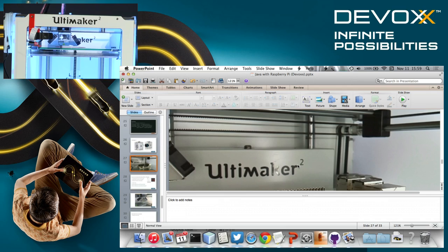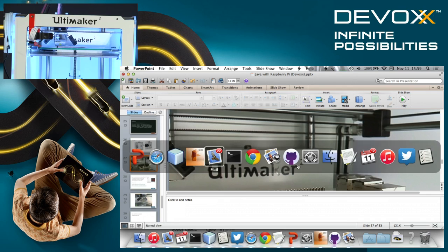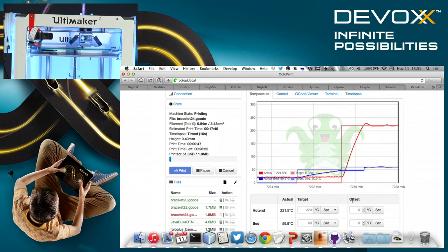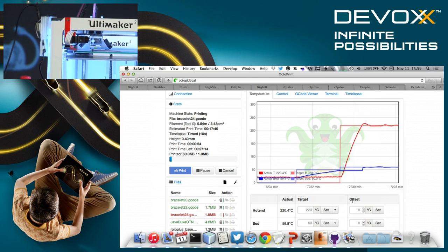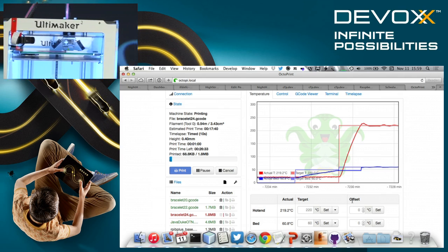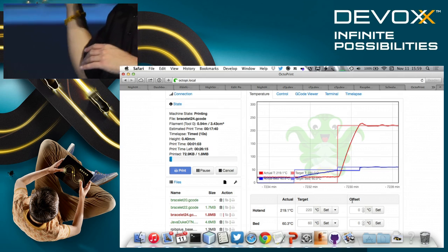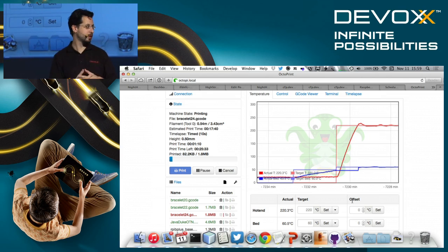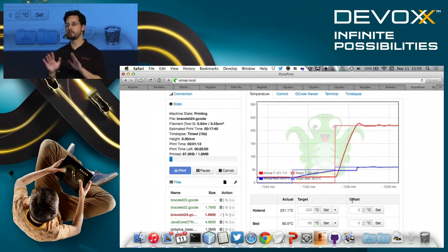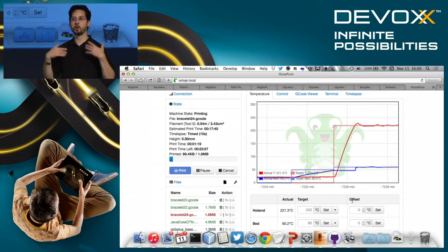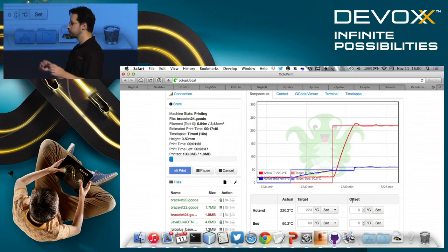And let me show you both the printer console that's going right now. So we have this printer, like a good IoT talk, the printer is wireless. So we're hooked up to it remotely via OctoPi. And OctoPi is running on our Raspberry Pi on the side of the printer. So this allows us to remotely control the printer via USB. And you can see the blue line is the heated bed. So that's the temperature of the bed, the build platform. The red line is the nozzle temperature. So the nozzle, we're printing PLA plastic, which is a corn-based plastic, and that wants to be printed at about 210 to 230 degrees. Faster or slower depending upon how quickly you're printing, and how much flow you want to get out of the print head.